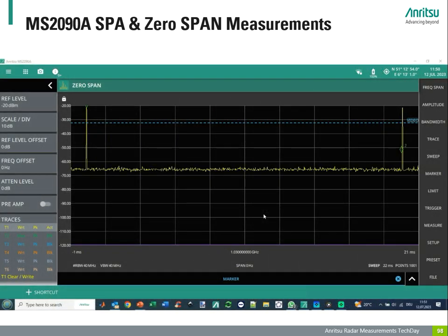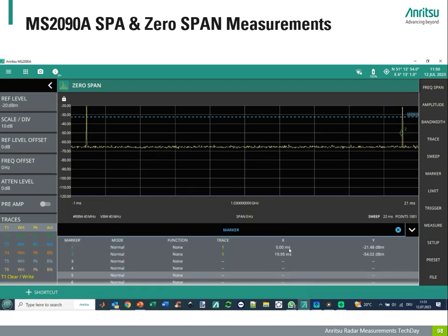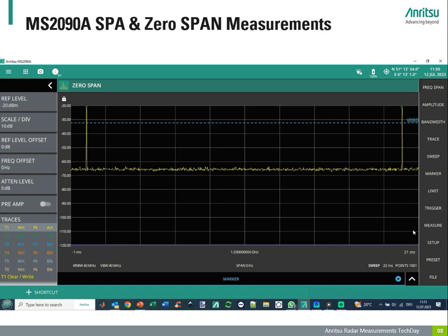Mode S interrogations are generated at the rate of 50 Hz PRF. Mode AC interrogations come with a PRF of 230 Hz. For sure, setting the markers more precisely would reveal even more exact values. The observed duty cycle is 0.1%. This is a very low value that could cause trouble with other instruments.